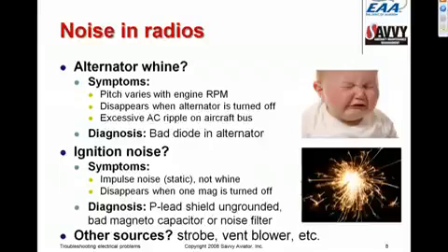The most common reason for that is that where the shield is grounded to the mag inside the engine compartment, the shield has just fatigue failed because it's subject to lots of vibration, as is anything that's hung on an engine. And if the P lead shield ground gets disconnected, that P lead, which is no longer shielded, just becomes a big antenna that radiates ignition noise into all radios and so on. So that's the most common reason for ignition noise.